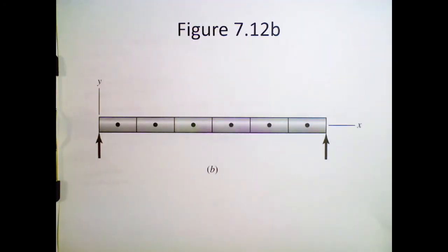equation 7.23. This is an image of a similar shaft, but in this case, we're taking the shaft and dividing it spatially into discrete segments. And by creating these divisions, we can improve the accuracy of our estimate. We can also take into account varying mass. So for example, if there's a segment where we have a component attached that's heavy, like a gear or flywheel, we can take that into account when we are calculating what the overall first critical speed for this shaft system is.